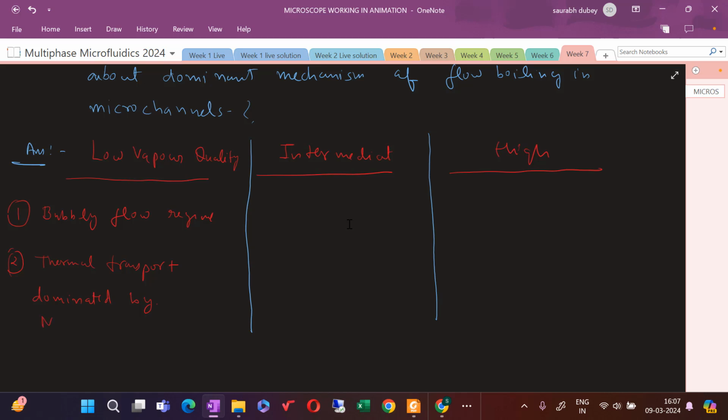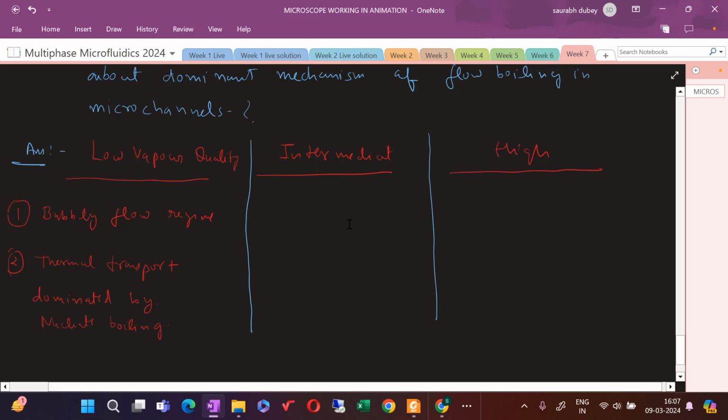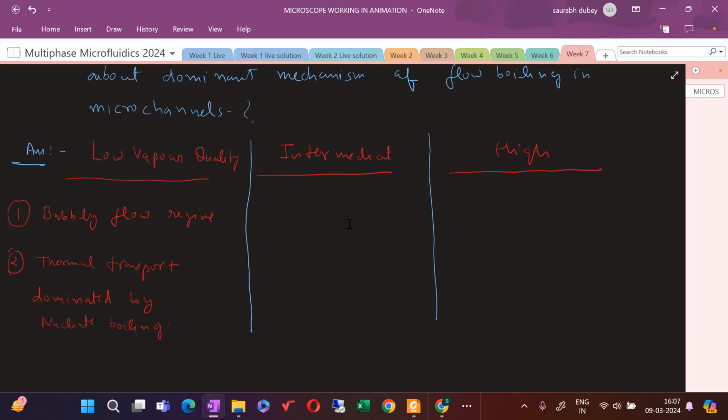Okay, dominated by nucleate boiling. That's the one thing. In the intermediate regime, there will be passage of elongated bubble and the slug of liquid.